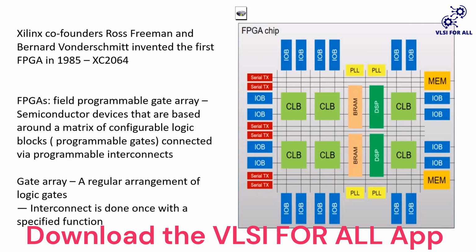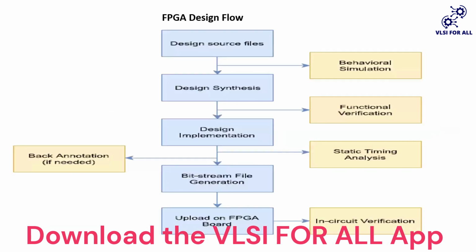You can easily learn them. For FPGA, this is the initial language. As in the step I am showing right now in my slide, in the first step we complete all the coding, and then we move to synthesis. If your code is ready and you know your design and how to implement it, synthesis is a direct process given in your tool.